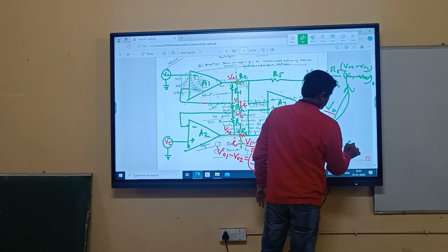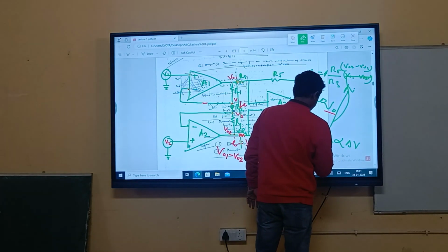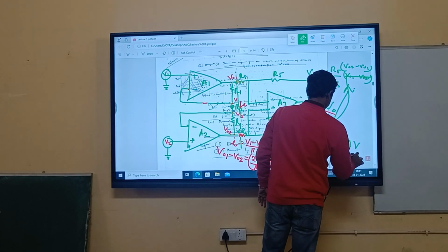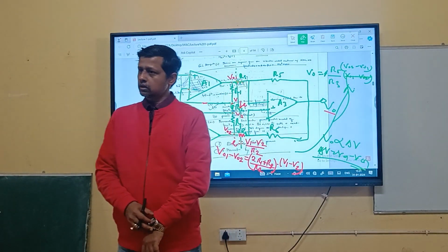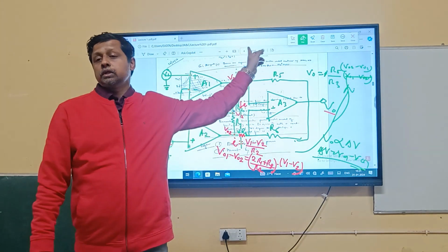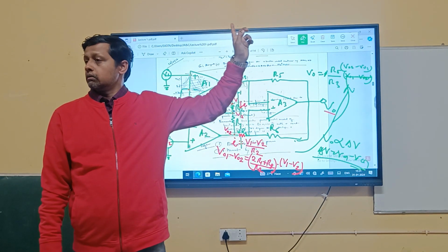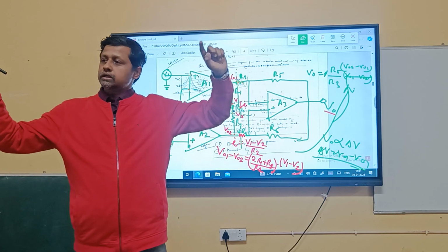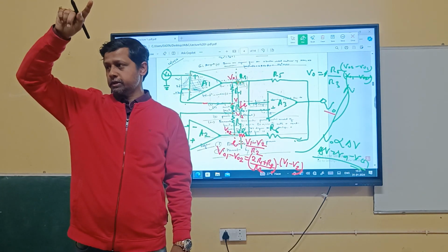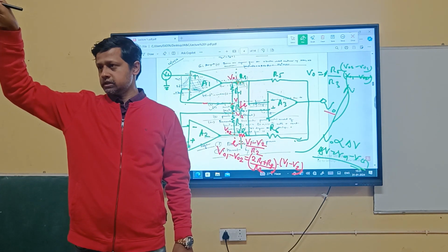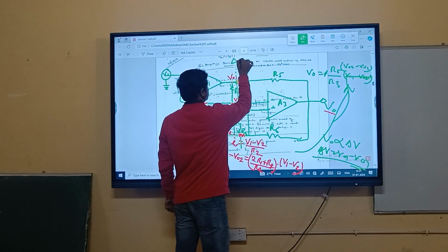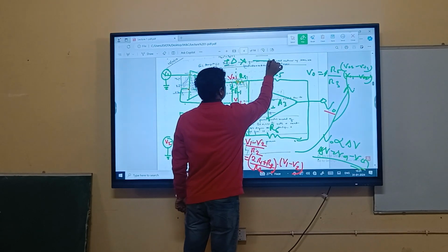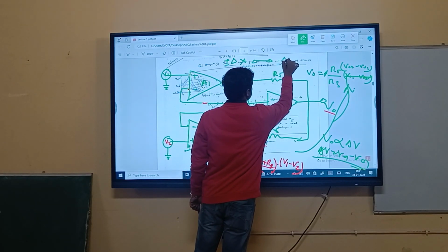V0 is proportional to delta V, where delta V is equal to V01 minus V02. Is it okay? Got it or not? What was your objective there? What was the output? Absolute acceleration was converted to relative displacement, plus or minus delta x. Now plus or minus delta x will be converted to delta V or not?